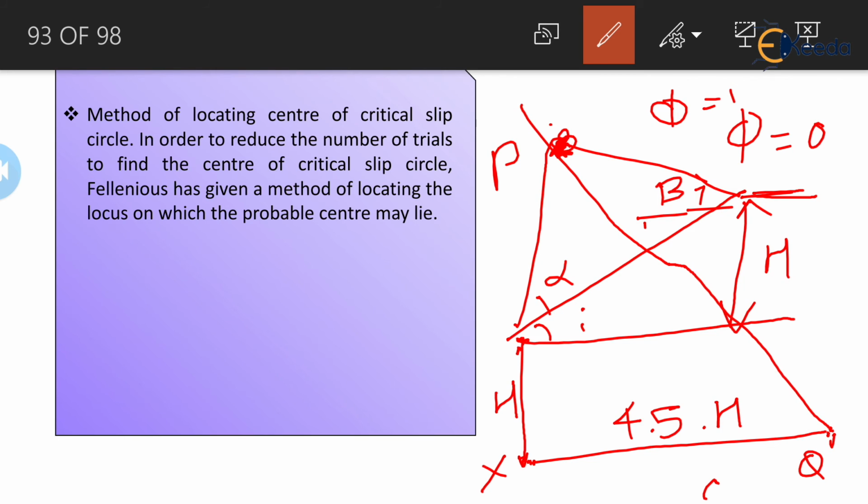The factor of safety corresponding to each center is calculated at each distance where we plot a center. After getting the factor of safety, we plot it as an ordinate in a vertical manner, parallel to the upstream section, and a smooth curve is obtained. The center with the lowest factor of safety is the critical center of the given slip circle.